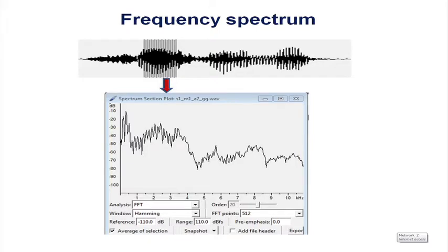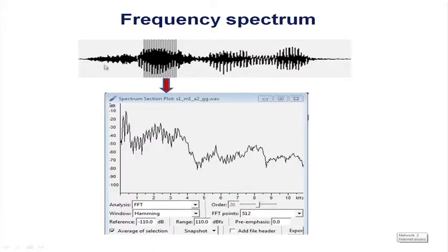Now, I come to the application side. So, where do I use the DFT or frequency transform in speech? Suppose I have a time domain signal, I already showed you the time domain signal, and this portion I have selected, this portion of the signal I have selected and take the frequency response of the signal. Now, there is a point, if I take n equal to 1024, that means the order of the DFT is 1024. So, I take a 1024 sample signal.